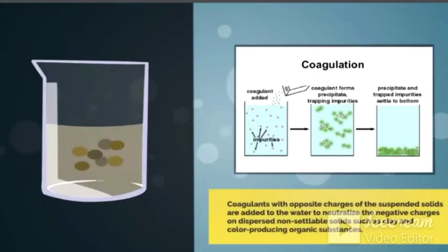Coagulants with charges opposite to the suspended solids are added to the water to neutralize the negative charges on dispersed non-settleable solids such as clay and color-producing organic substances.